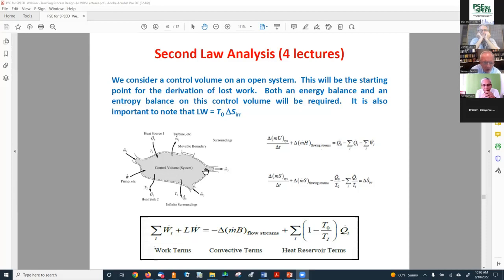So we need to know what's coming out, flow rate times the enthalpy, minus what's going in, flow rate times the enthalpy, and similarly for this, that's this term. Now we have to have the heat. So this is now Q naught, and it would be positive if the heat is coming in there, because we're showing it here now as negative, it would be a negative number, and you get the idea.